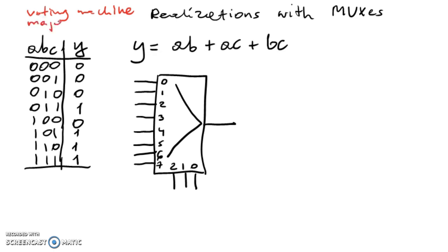It can be named majority of ones detector. And from the full adder, you know also that it is simply the cout output of the full adder, cout of FA.